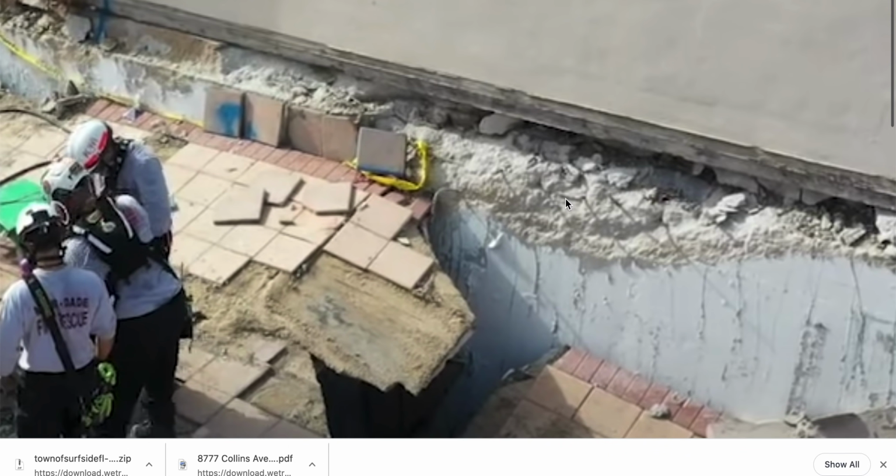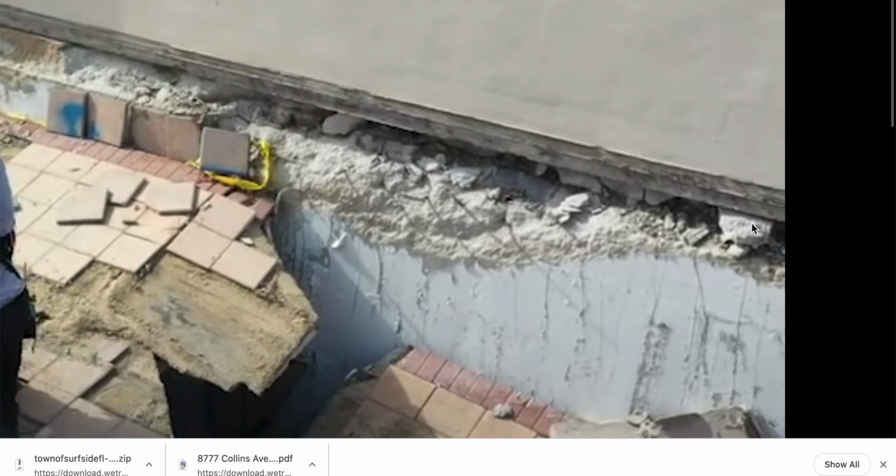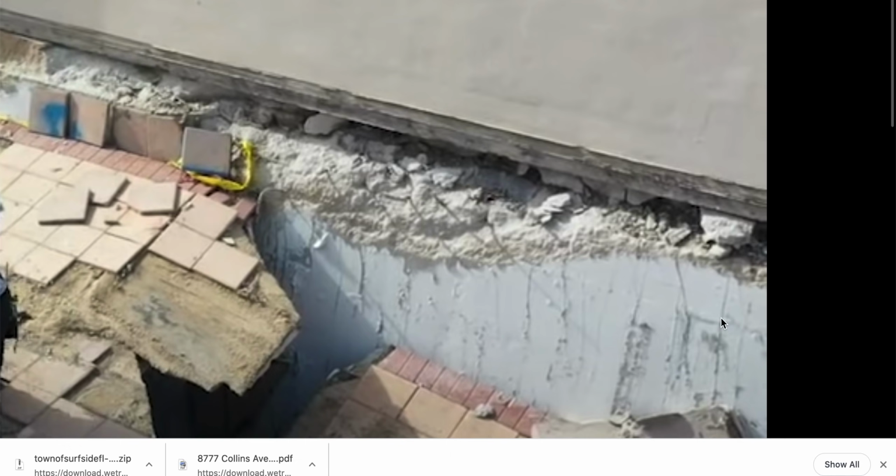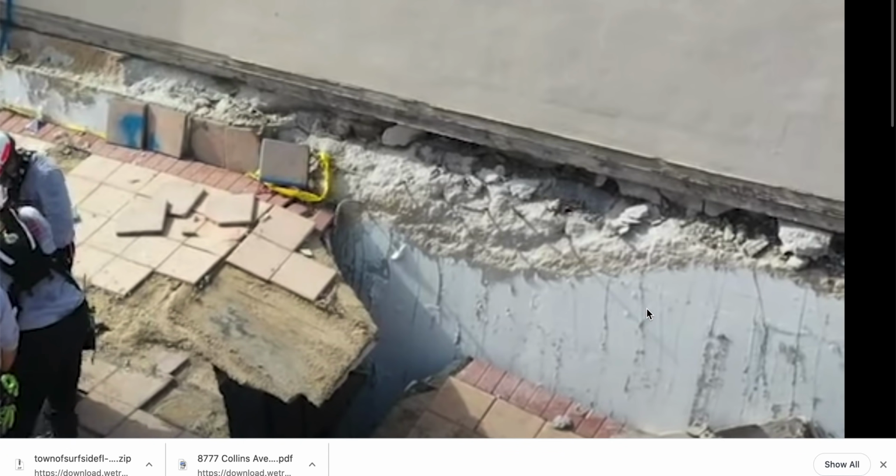So I see steel here. Now that engineer made it clear that she was there, and there was no rebar at this location, at this back wall. I see scratch marks down these walls that are indicating of like rebar, unless it happens to be the perfect spacing of the concrete sliding down and doing that. I see shadows that indicate rebar right here, reinforcement here.